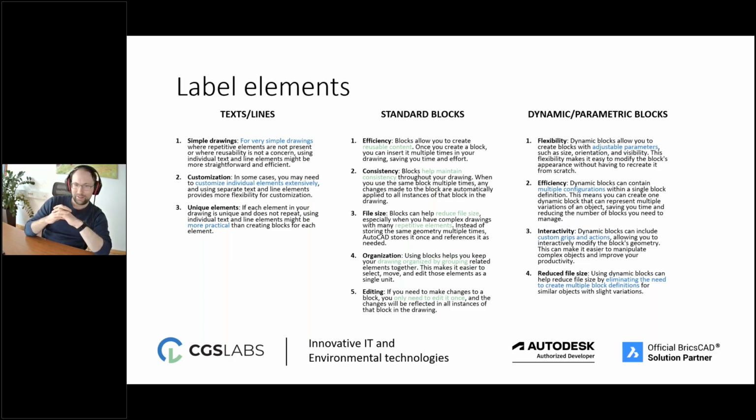And then one step forward, we have dynamic or parametric blocks in BricsCAD, which actually gives you a little more customizability. You have adjustable parameters. You can use multiple blocks in one block. You have the option for custom grips and actions, which actually gives you the customizability of individual elements on top of the blocks themselves.